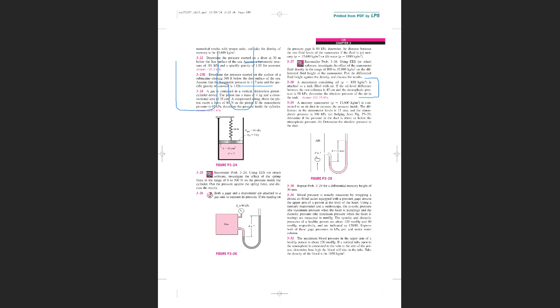Below, Doctor. He said below. He said the pressure inside the duct is below atmospheric pressure. Remember, this is atmospheric pressure here, because this is open. There is a fluid moving in the duct, and the manometer shows this shape. The fluid is being pushed up. His question is, the pressure inside the duct, is it above or below atmospheric pressure?